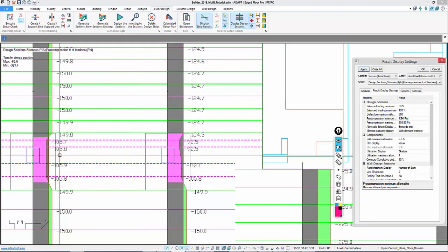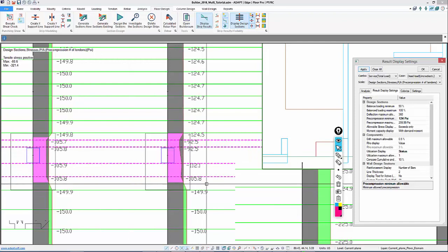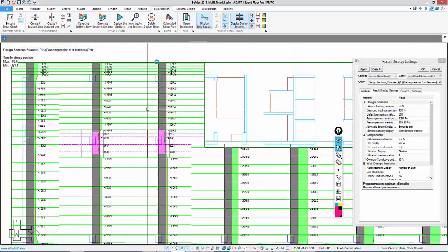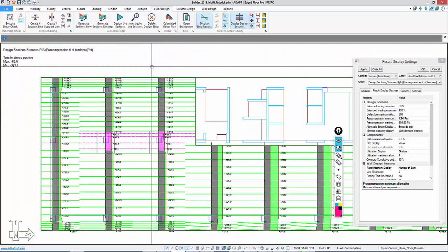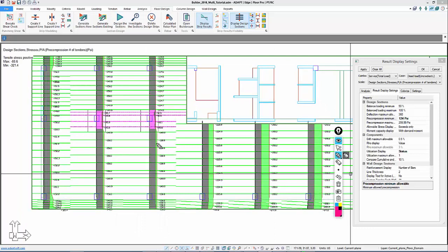So it happens mainly where we have a drop panel. If we have to bump up the amount of pre-compression through the drop panel, then we're going to have to increase the number of tendons passing through this location. We could do an add tendon that starts, for example, here, and run that out to feed that zone with more pre-compression. That's one way to resolve that. But we need to resolve any pre-compressive issues before we check stress. That might be just a natural progression in the design.